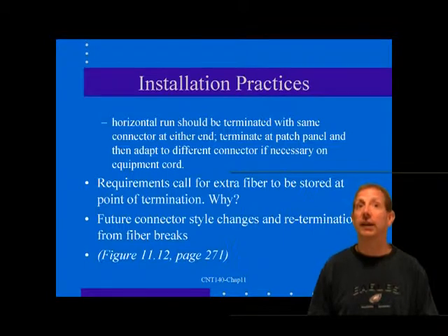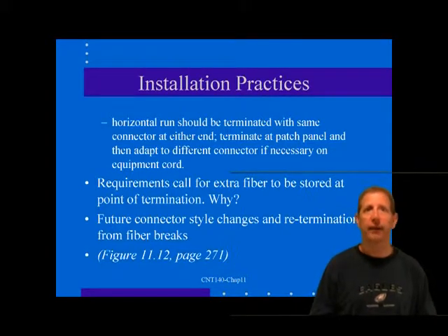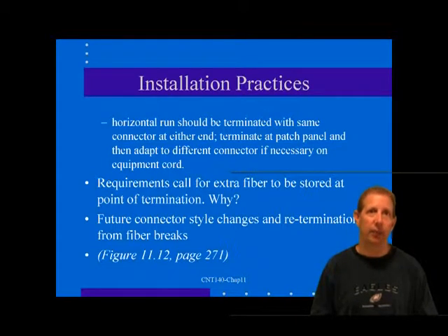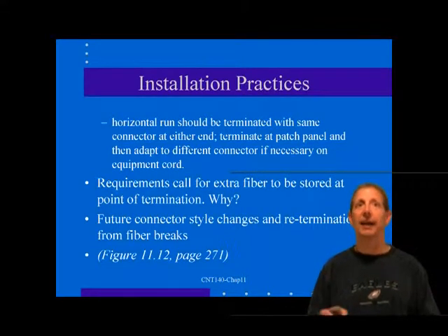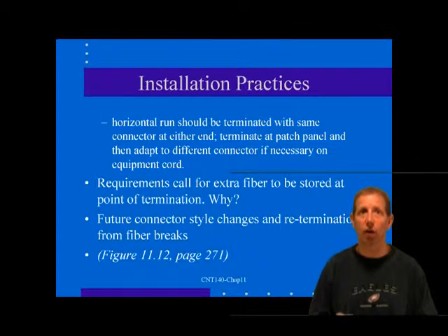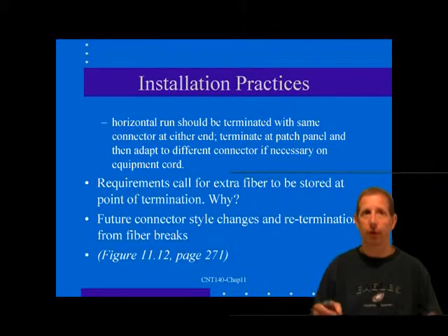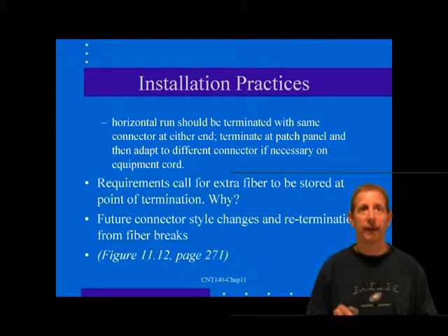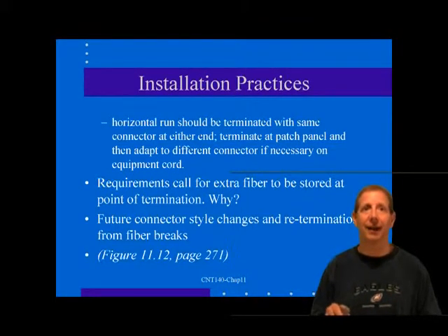Any nick will severely compromise the flexural strength of the silica fiber and may result in spontaneous breakage. The rule of thumb is that such a break will always occur at the last possible moment, so that the installer will have to start over totally. So the lesson is that no nick is a good nick, or nothing can truly be done in the nick